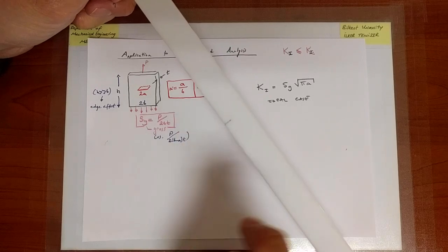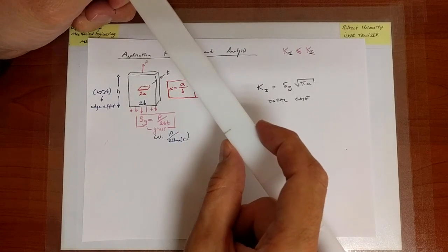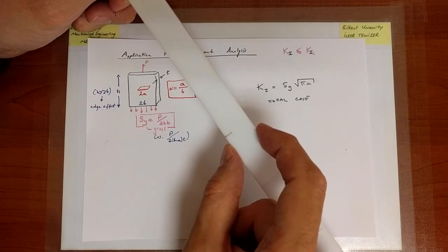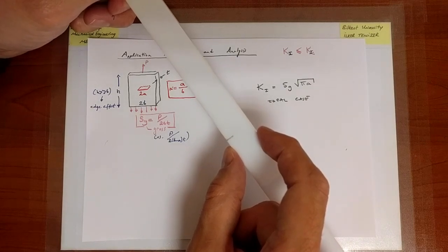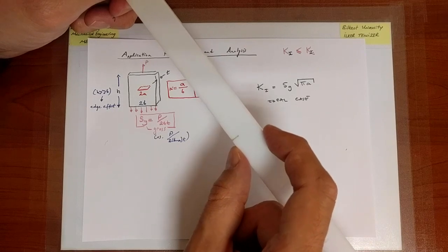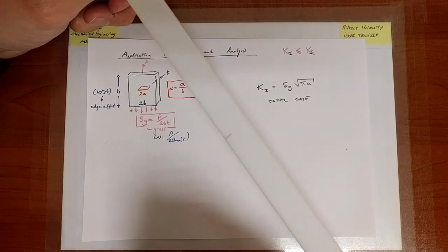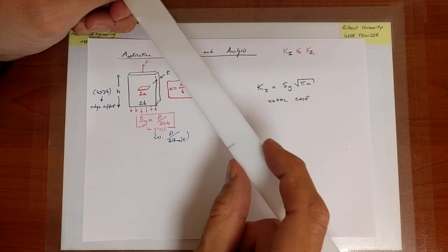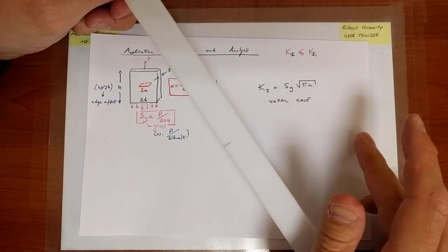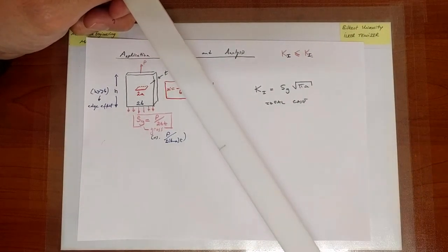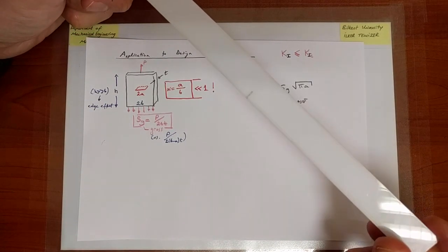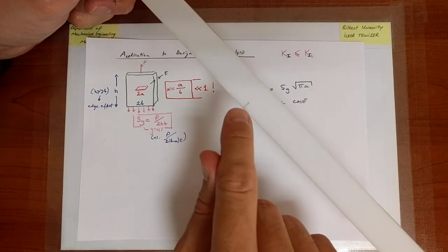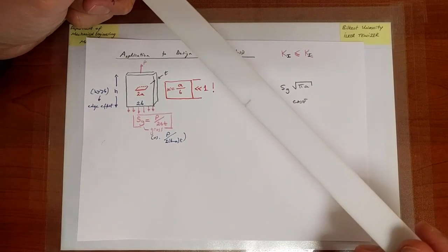Two, the width of the crack is probably not very small with respect to the width of the plate itself. Now, whether it is small enough or not is something that we will always debate, because the question of how small always comes with an answer to within a certain accuracy. We can say small enough according to this or that criterion. We're going to also introduce a measure of smallness very shortly, but probably in this case, the crack is not small enough. It turns out, indeed, it's not small enough.